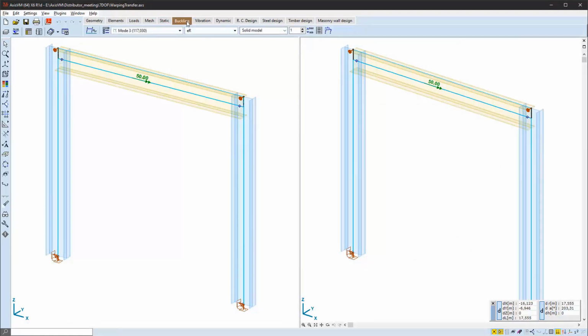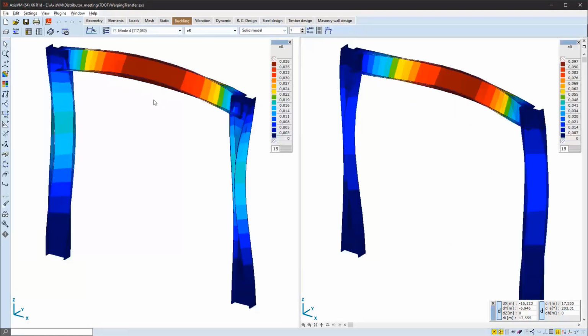And running the backlink analysis, you can see that in the diagonal case, the beam and the column rotation direction is the same, while on the box type, they are rotating in different directions. So this is how you can take into account this type of joint topologies.